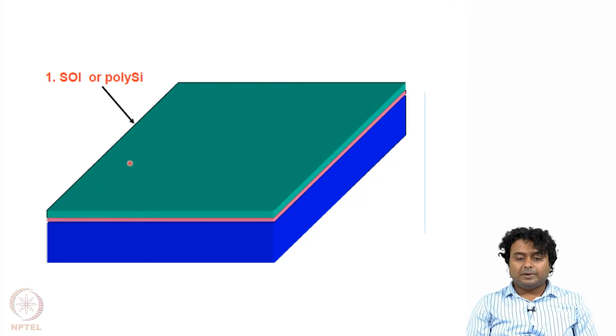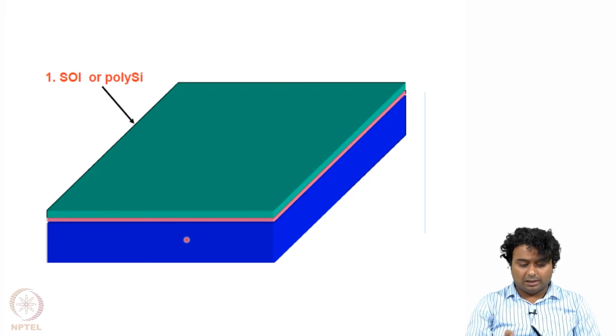Now, for making this we start with a SOI layer, or silicon on insulator. So, you see there are three different layers. The first, top one is the silicon layer, but in the middle, the sandwich layer, is the silicon dioxide layer, and the bottom is also silicon, which is single crystal silicon. Now you see the basic difference. So all are silicon here, right?